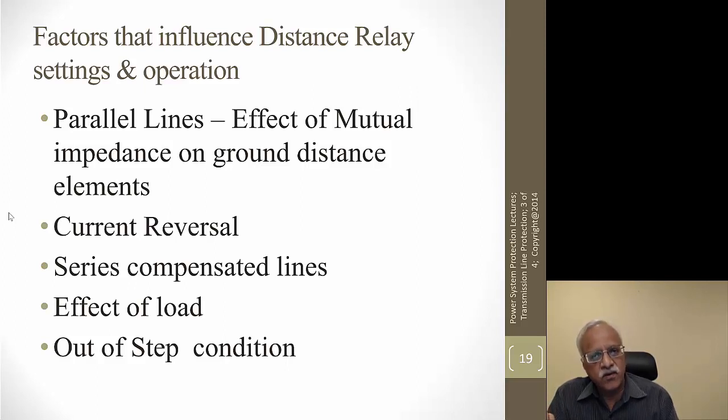The effect of load also has some impact on the settings and on the operation, especially if it is a long line, so you select settings so that you don't want the relay to operate under load conditions. There are also what are called out-of-step situations, which we are not covering in the basic courses.